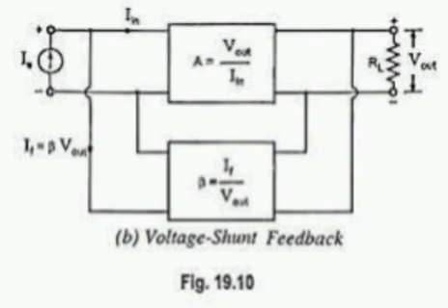Total DC power supplied to an amplifier PS equal VCC into IS. Maximum AC load power PL max equal PP square by 8 RL, where PP means maximum unclipped value of VPP. Stage efficiency eta equal to PL max by PS into 100%, where eta means stage efficiency, PS means DC input power. Class A amplifier produces least distortion in output among all power amplifiers. The maximum efficiency of Class A amplifier is 25%.